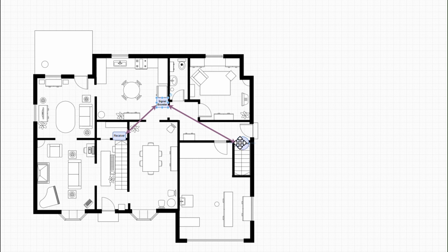Same would apply if a thermostat was upstairs. Then you would have the ceiling to go through. I haven't actually got a second floor here, but let's say that was upstairs. Then the signal booster, if you placed it at the bottom of the stairs, you've got a nice clean path for the signal to go through to here, and then from the signal booster straight up the stairs to the thermostat, or up through the ceiling to the thermostat, which should be a much easier path.